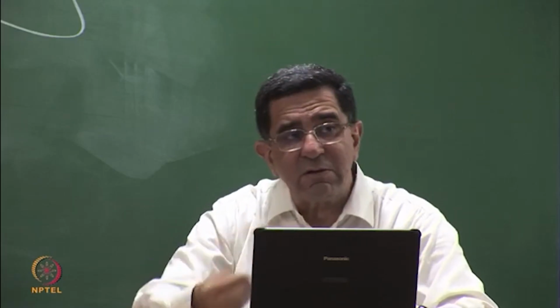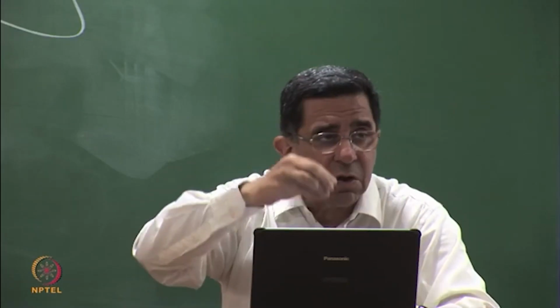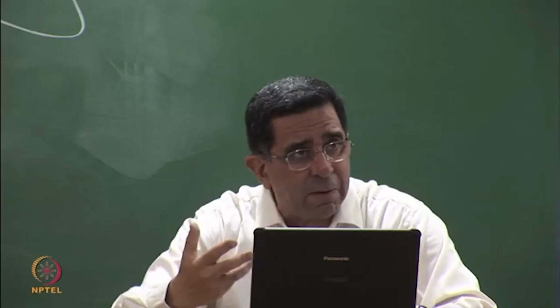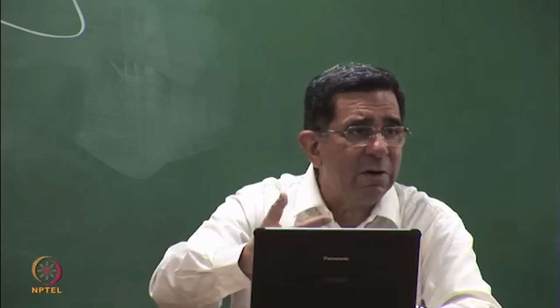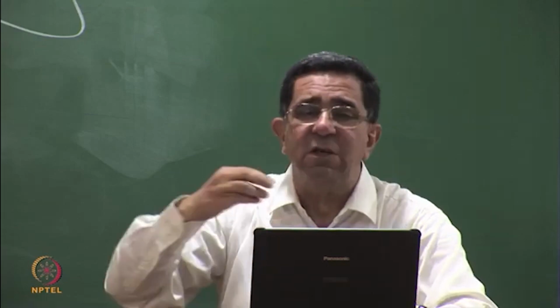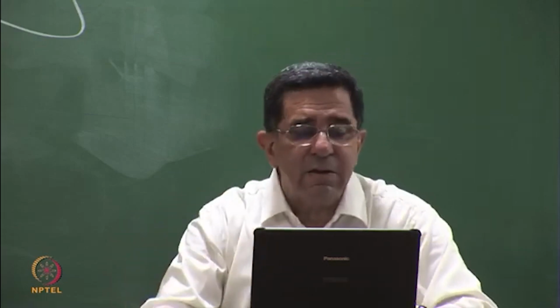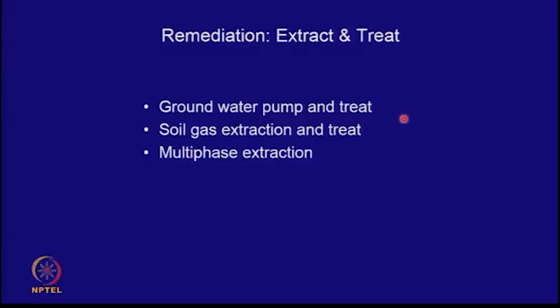It also means that the groundwater that you have injected has also washed the soil particles, so that if there were any contaminants on it, they have been released into the groundwater, which has been again taken out and treated. So groundwater pump and treat is very often adopted as one of the ways of contamination control. It's not a simple process.